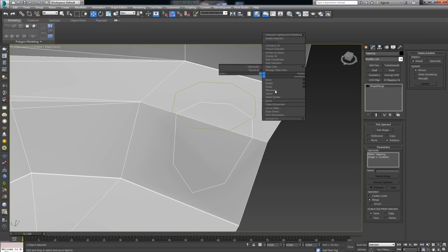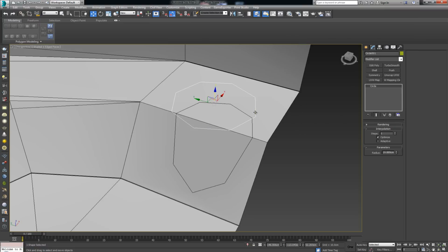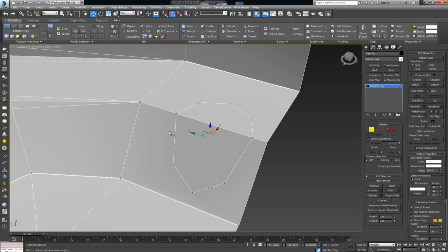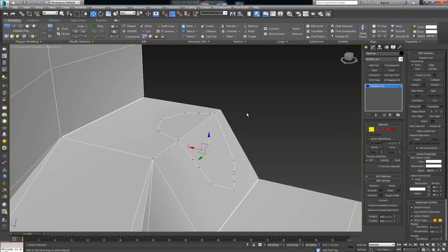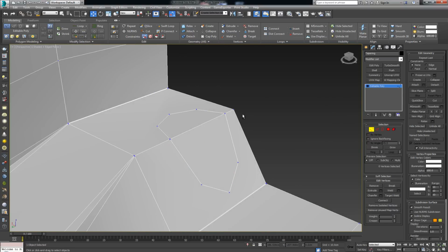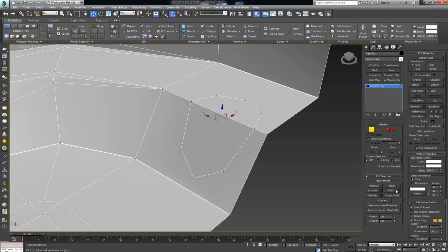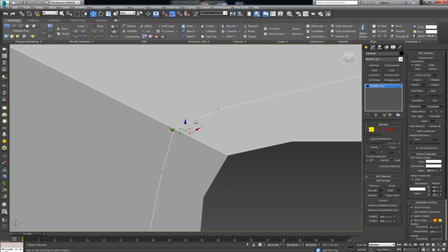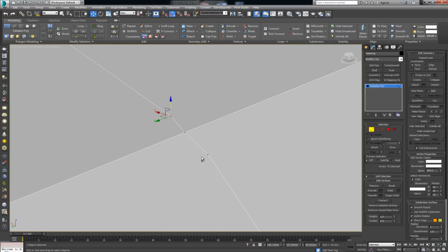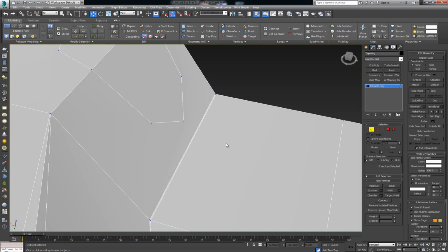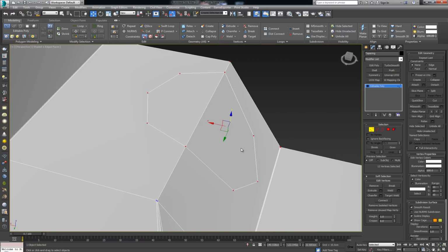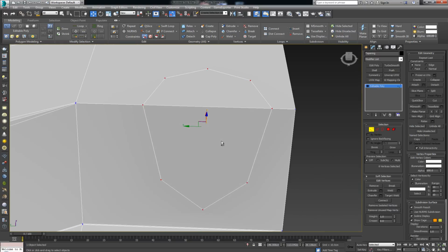All right, again, right click, convert to an editable poly. Delete this. Again, make sure we don't have any extra vertices. As you can see, I have some over here. Select all the extras that you don't need. Control Backspace. And I'm going to select all of these vertices over here, go with the weld. And as you can see, from 77, they drop down to 72. So that means I'm not going to have any double vertices as I have here. So Control Backspace. Just need to make sure that I'm really clean, because it's going to be a pain trying to deal with something that's really not visible here. So again, increase. All right, no problem so far.